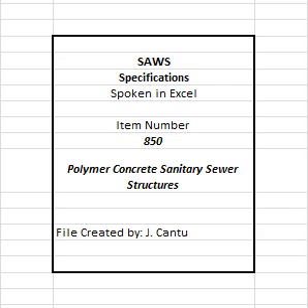850.3 Submittals. Contractor shall submit manufacturer's product data, instructions, recommendations, shop drawings, and certifications. All submittals shall be in accordance with engineer's requirements and submittals shall be approved by the engineer prior to delivery. 1. Submit shop drawings for each structure. 2. Drawings shall include station number, location, rim and invert elevations, dimensions, reinforcing details, joint details, and component parts, base units and construction details, jointing methods, materials, and dimensions.